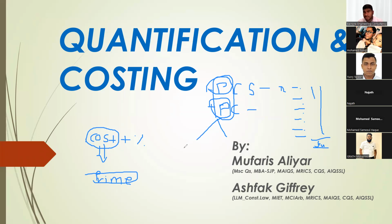So these three should be the cost of the contractor. Now, the PC rate we are putting in the bill of quantities is the prime cost of the material only. So that allows the contractor to add his plant as well as his labor to price in the bill of quantity. For example, we give a PC rate for a porcelain tile of 40 dirham per square meter. This 40 dirham per square meter is just the cost of the material.